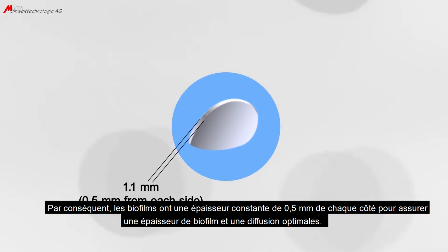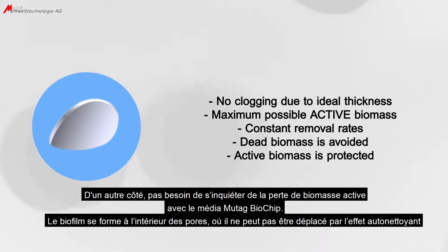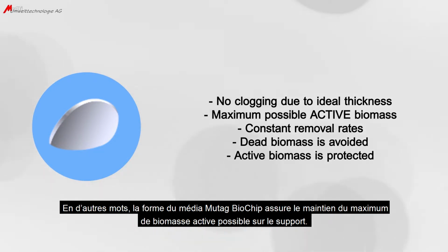Consequently, the biofilms are permanently kept at a thickness of 0.5 mm from both sides, whereas an optimal biofilm layer thickness and optimal diffusion is attained. On the other hand, there is no need to worry about a potential loss of active biomass on the Mutag BioChip. The biofilm establishes inside of the pores, where it is protected against being flushed or sloughed off by the self-cleaning effect. In other words, the geometry of the Mutag BioChip ensures that the maximum possible amount of active biomass can be permanently kept on the carrier.